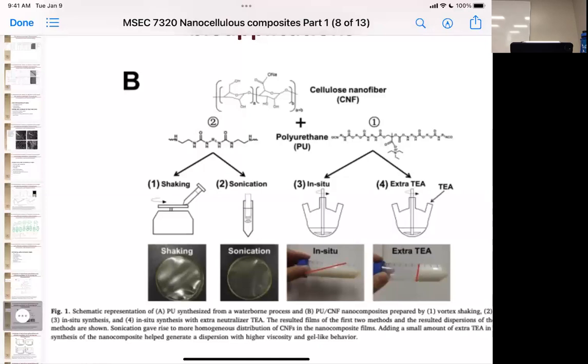You're having a neutralized fiber that gives a gel-like appearance, which gives it a nice shelf life. So now, what's the other benefit of having this here? If we're going to 3D print, high viscosity makes it easy to print. You don't have to heat it up, but also it doesn't drip. The high viscosity also makes it more precise, and you're assuming it shear thins a little bit to get through the nozzle, but then it immediately sets up again. That's good, I think, extrudability.